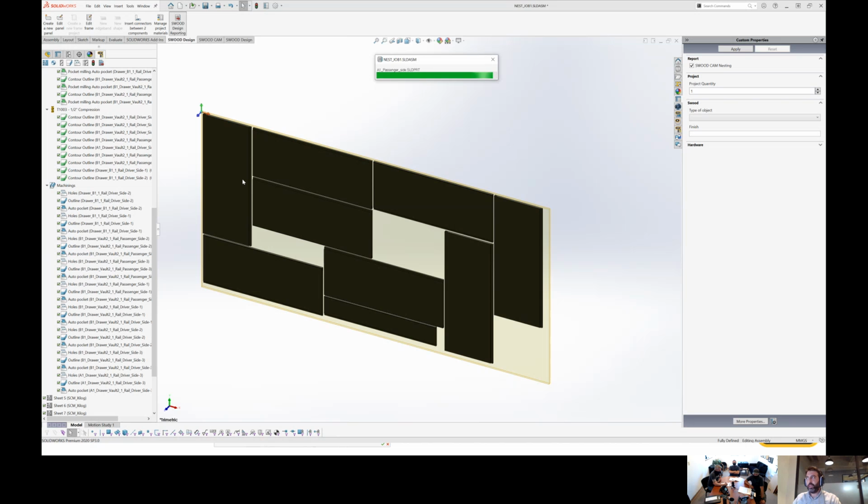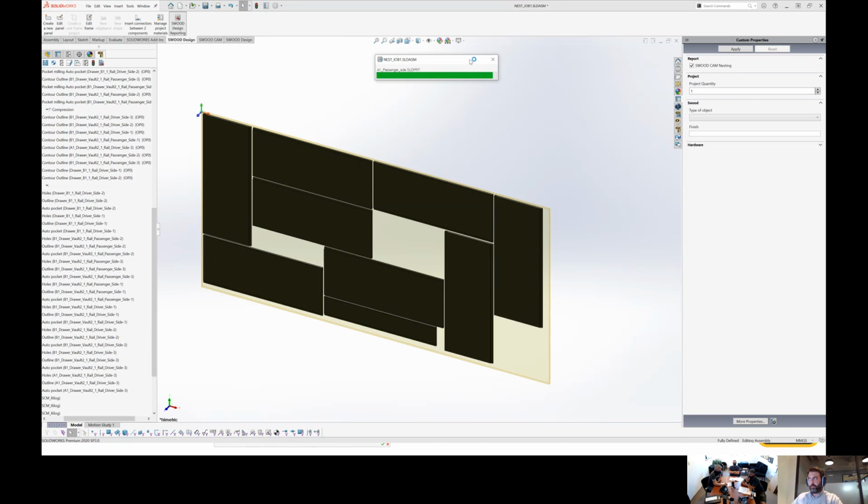Yeah. Okay. The main one, because we've tried tabs and onion skin and all that. The biggest benefit to us with our current nesting software is you can drop in a bit on a long cut, and that bit won't come out until every piece is cut. So you'll basically go around half a part, then go to the next part, cut out half of it, and it just continues on a continuous path. We call it bridge nesting, but I don't know what other term is out there.